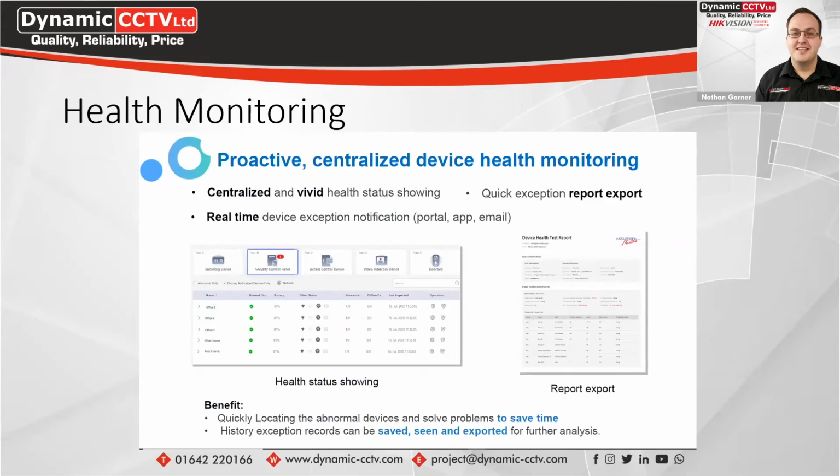So you can see if there are any faults on the system and deal with them accordingly. It may be just a setting that needs changing, which you can then dial in through the same web page. Or if it's a detector that's failed or a power failure, you can then arrange with the end user or client to attend a site visit to resolve the issue.